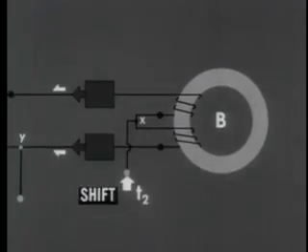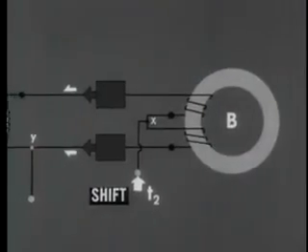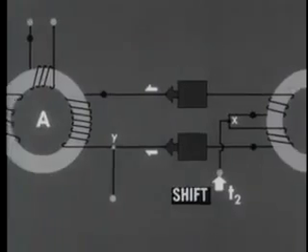The diodes conduct in this direction, and the two branch currents flow toward core A. But the lower branch does not get there. Instead, it flows out of the circuit at point Y. The upper branch, however, does reach core A, entering its output winding as a dot pulse. Since core A is in the binary 0 state, that is, its magnetic flux is already negative, an additional pulse of dot current will have no practical effect on the core.